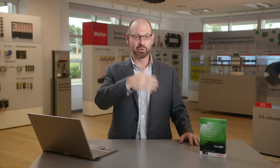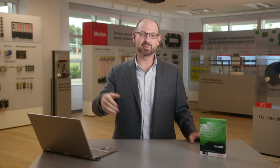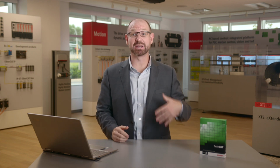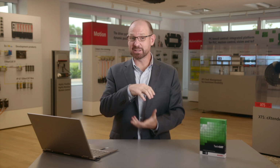Second one is when you multiply those into multiple cameras, so you have an application with 5, 10, 15 cameras, the cost for each one of those pieces of hardware gets exponentially more. The other approach is PC vision. So you bring the vision back, you do it on a PC, which is great, you get a bigger processor, but you're a little beholden to the operating system. When you bring it in, the processing speed is also doing operating system interrupts and checking network settings and all that good stuff that operating systems do. Another approach on the market today is a hybrid system. So it's a dedicated vision PC, but they're extremely expensive and they only do vision. You can connect a couple of cameras.